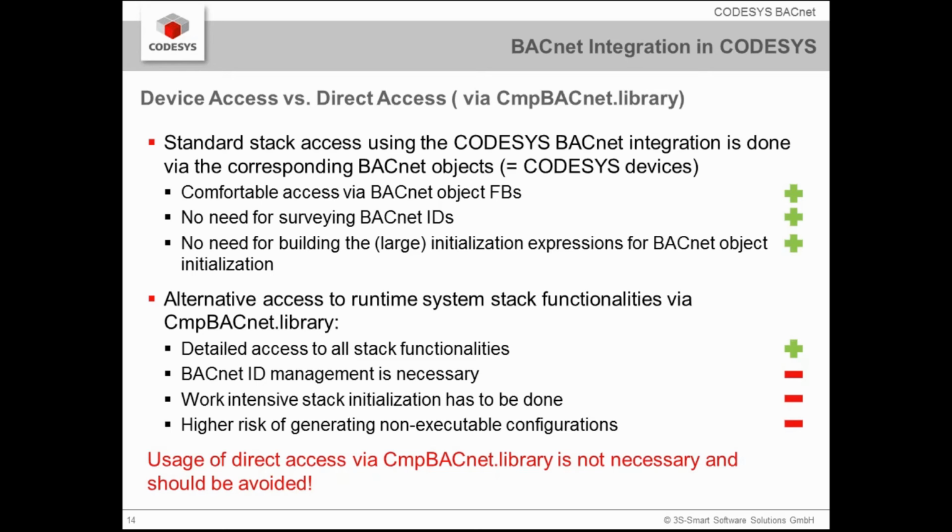The disadvantage is that you have to take care of BACnet ID management, and you have to take care of the really work-intensive stack initialization, and of course you have a higher risk of generating non-executable configurations. So the usage of the direct access via the component library is possible, but is really not necessary and should be avoided.